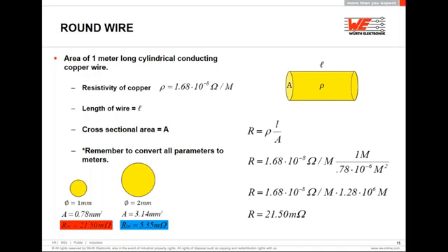As you can see, the bigger yellow circle on the bottom left corner shows a diameter of 2 millimeters. And we've applied the same calculations and we got the following results. The cross-sectional area is 3.14 square millimeters, and the direct current resistance would be 5.35 milliohms, which is around 4 times smaller than the previous calculation. And this is considering the same wire length and material.